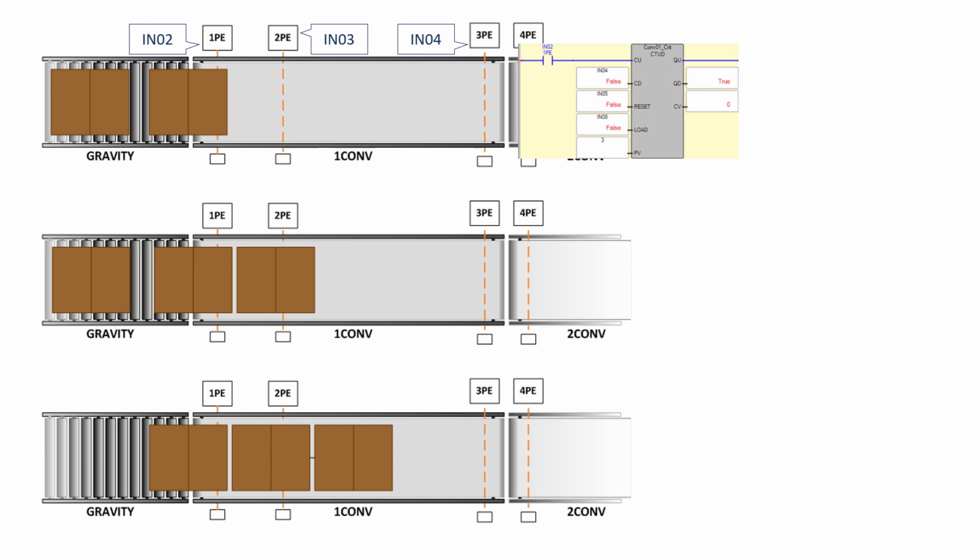Our counter data type has a process variable of 3 because we're saying that you can't have any more than 3 on the conveyor. We can't fit any more than 3 on there. And right now our control variable is 0, meaning none counted on. I don't have these cartons moving in our illustration here. But when the carton rolls down the gravity roller conveyor, hits the leading edge of conveyor 1, if it's energized, it pulls it on and breaks photo eye 1, and now we count up.